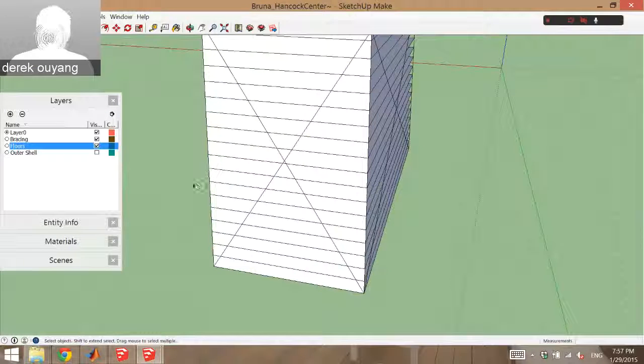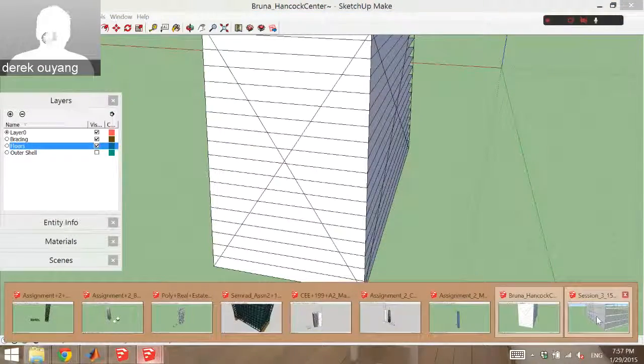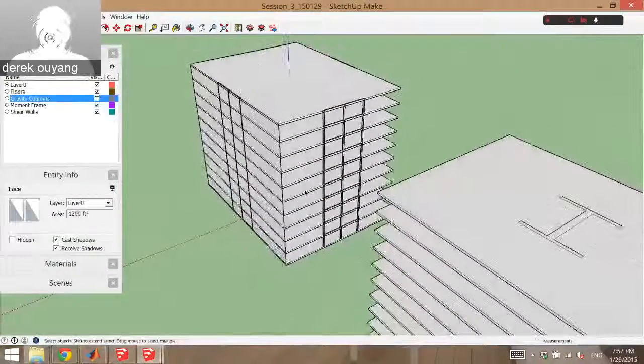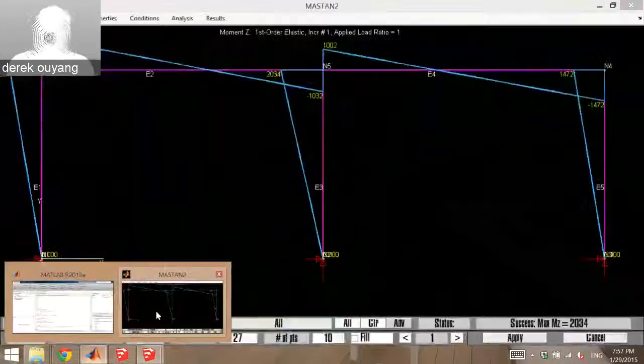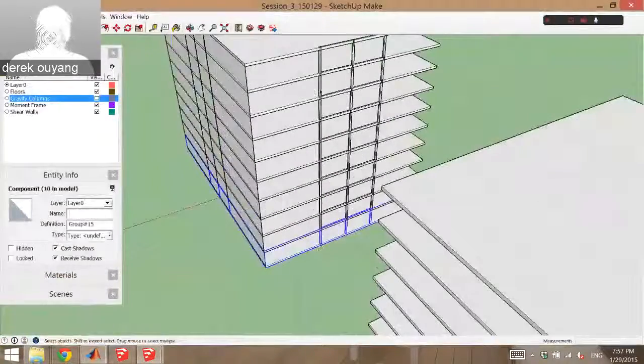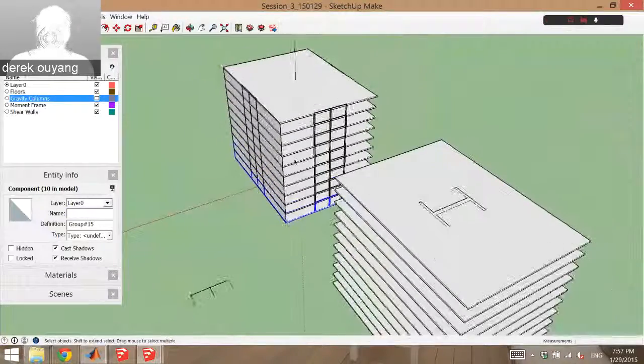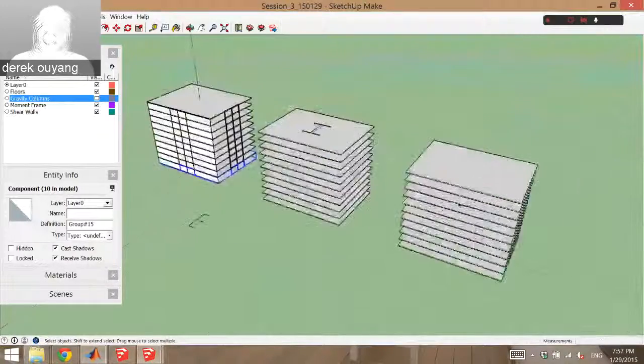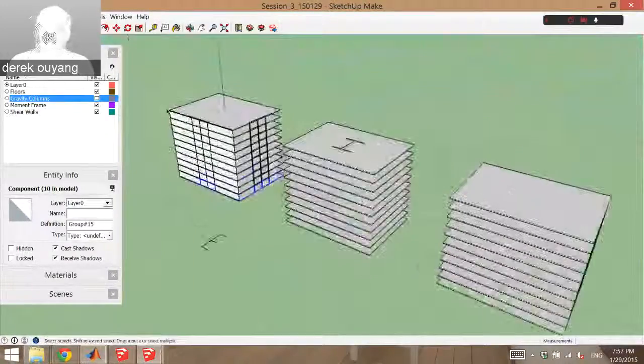For this example, but for the assignment, when you get to the third one, do model it for the full scale 10-story tower, or choose something comparable of your own tower. For the other ones, do model the entire thing. I was just doing one story to go quickly through that. But for assignment 3, you're going to model this 10-story thing right here with all the loads, because that will give you the accurate lateral system for this building. And for the shear wall, you want to model it all the way to the top. And for whatever you do here, do the same. So how exactly do you want us to model the shear wall? I'm going to get to that very soon.